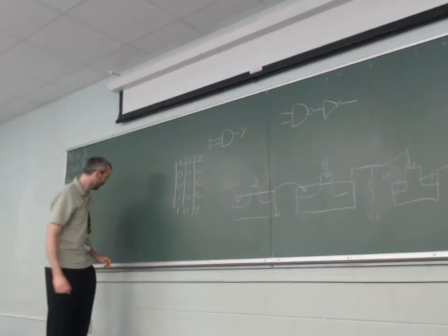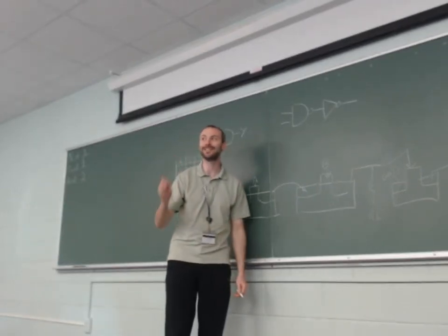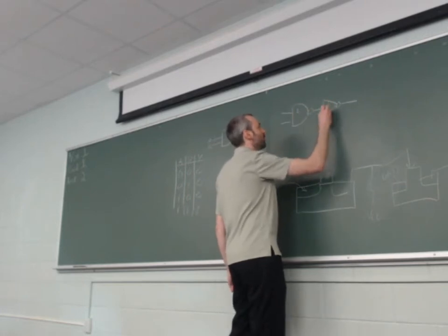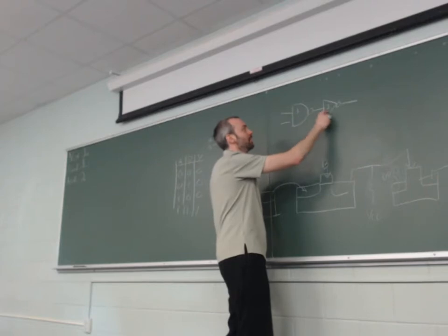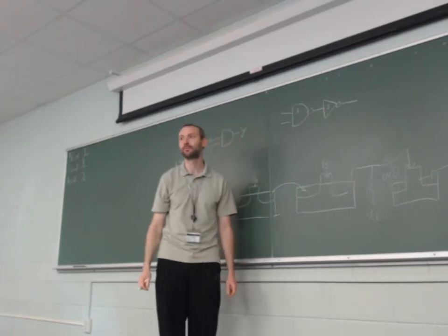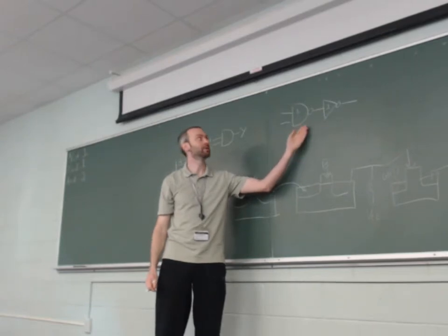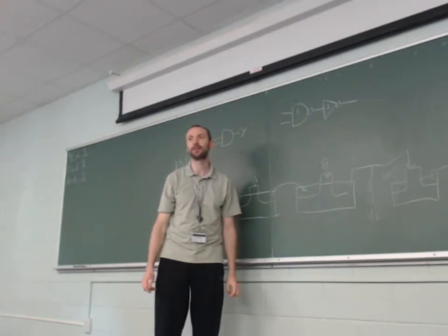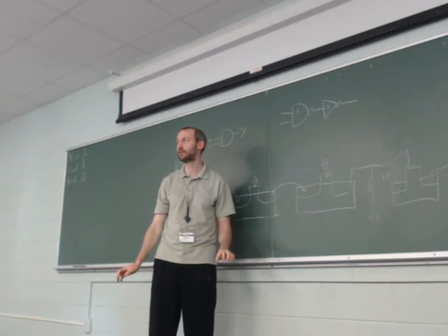You get this? Yeah. Another way to look at this, and this will probably be easier, and this is why drawing the diagram is way better. This is 1 gate delay. This is 1 gate delay. This one depends on the output of that, so you're doing 1 plus 1. When you start evaluating, you're going to be looking here. I'm just writing it down here so you understand low level what's happening.